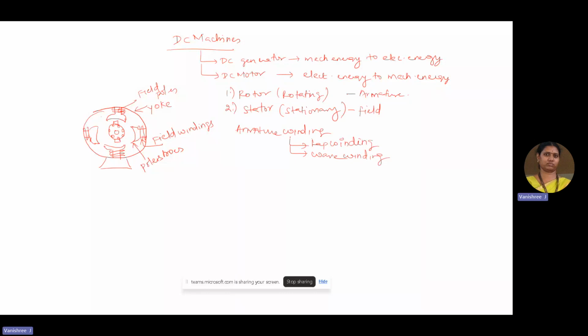So as we have a pair of brushes, the net voltage drop across the brushes is equal to 2 volt. It is the brushes which slide along the conductors and collect the current and provide it to the external load circuit. So this is the construction.